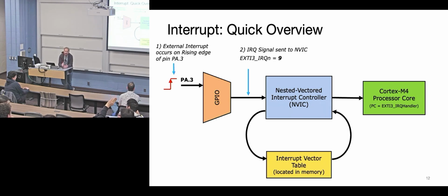Way up there, yeah. The stack goes toward lower addresses, so if you have a microcontroller with more memory, you want to put the stack close to the end of the memory so the stack has the most possible room to go. Right. So to restate that slightly differently, that was the correct answer.